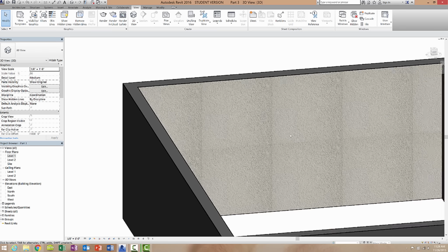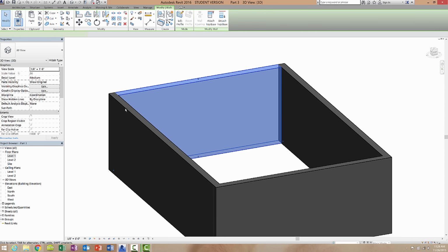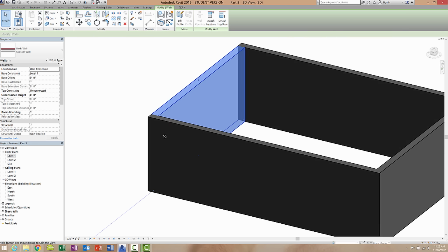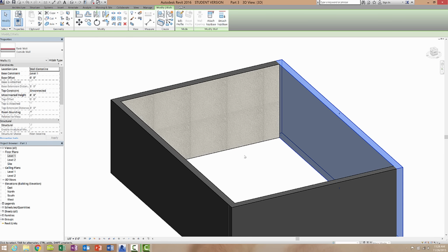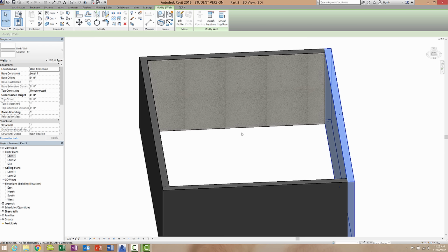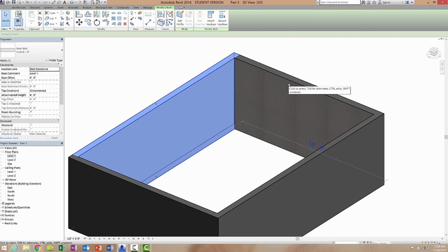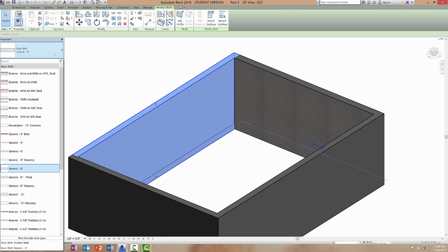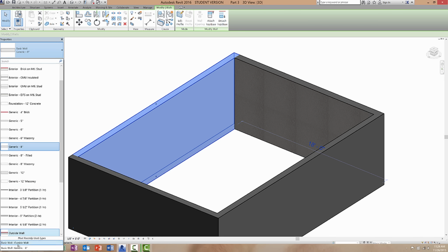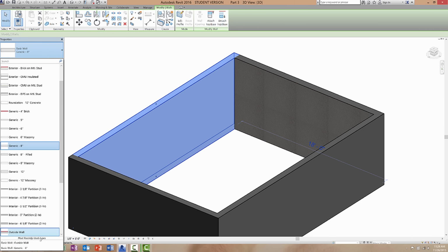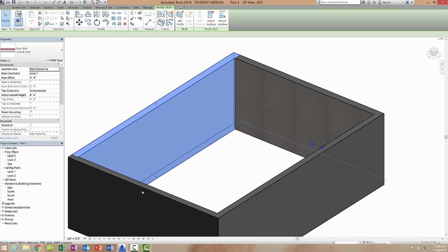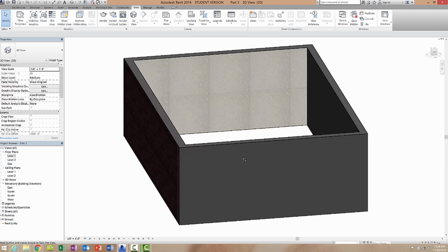So in the last video, we went ahead and created an exterior wall. You might have noticed that the other walls do not match this type, and that's because they're still set to the generic wall type. And we did that on purpose. We could have easily modified that exterior to this type, but we duplicated it instead because now what we can do is select our basic wall, and we can just go to the outside wall we created. It's located usually on the bottom in the most recently used area, and we can click on that and we'll automatically change these walls as well.